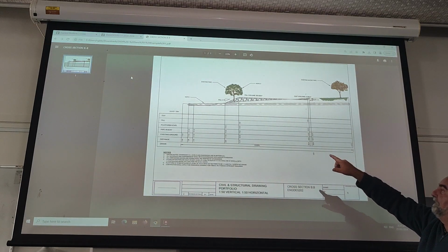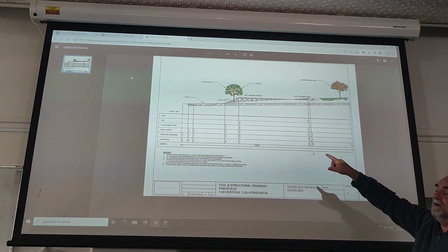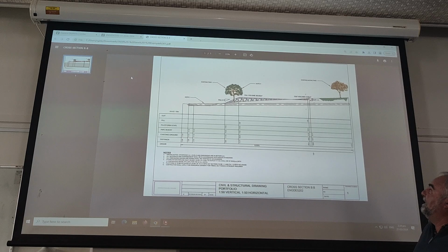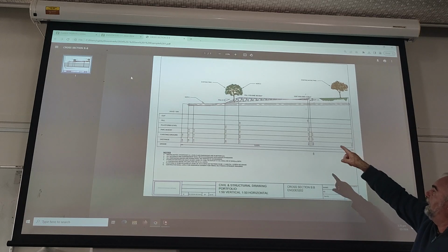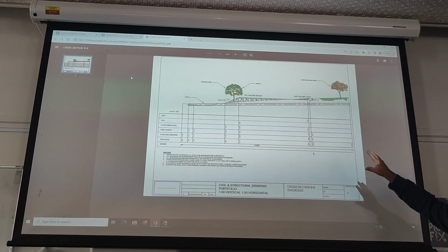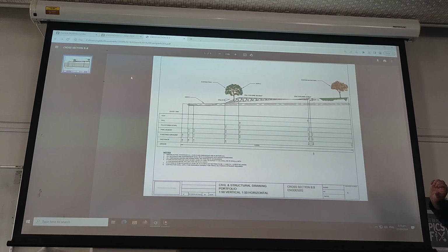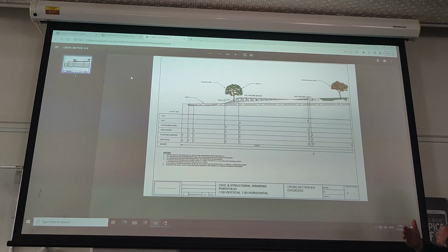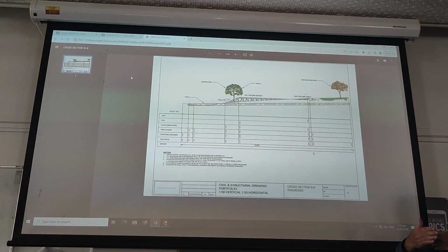Doesn't it look silly when you've got a little thing saying note 1 and the arrow size is almost twice the size, right? It's such an easy mistake to make. They have put the cut and fill volumes there. It's really good. Happy with that. The pipeline, they put a nice solid line. Unfortunately, that's wrong because the cut line was back here, and they're not cutting through the pipe, it's behind, so it should have been dashed, and no centre lines.